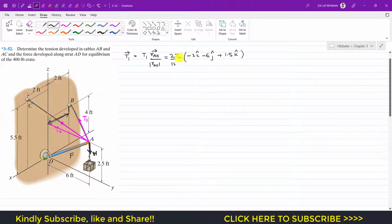So now we can further simplify this. I can multiply this 2 divided by 13 T1 into each and every component. So that T1 vector is equal to 2 into 2 is minus 4 divided by 13 T1 I, and then 2 into minus 6 is minus 12 divided by 13 J, and then 2 into 1.5 is 3, so that is plus 3 divided by 13 in the K. So this is the Cartesian vector representation of the T1.